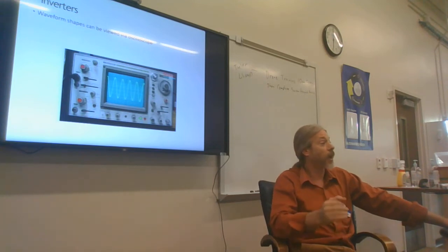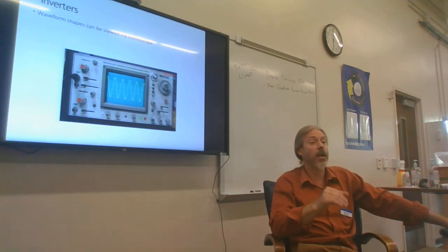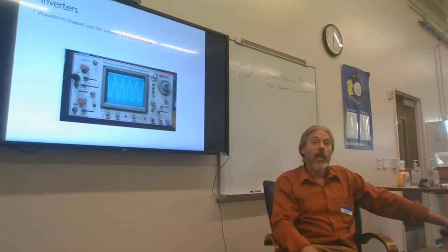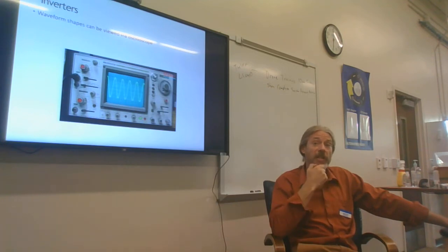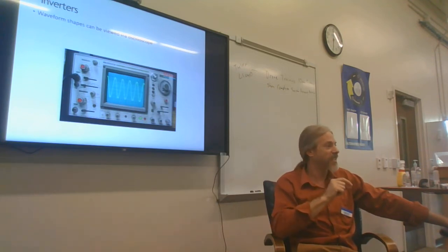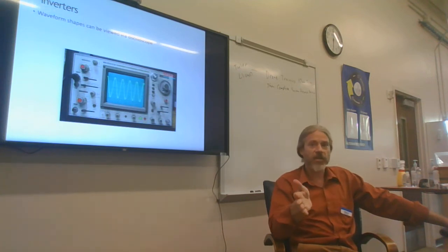Now, I will tell you that an oscilloscope is an unbelievably handy tool for advanced electrical issue diagnosis. In fact, every vehicle that has a computer that will put out codes that you can hook up a code reader to, all that code reader is doing is reading the electrical signal sent out by this device.